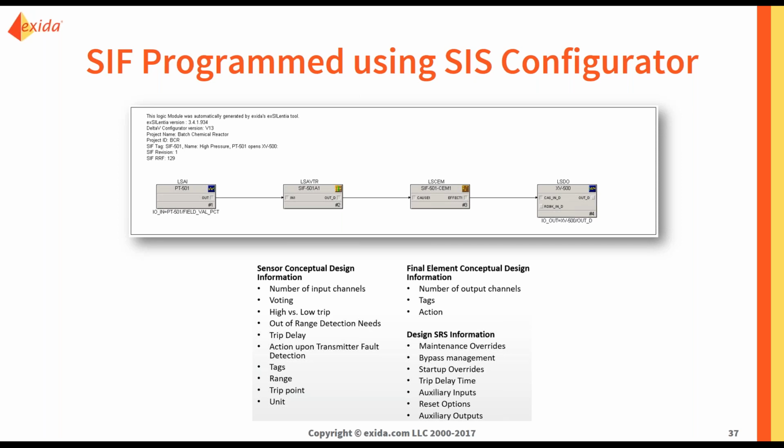For your sensor conceptual design and your final element design, all of the things you need to know, the tags, the action, the set points, etc. are in the tool. And so this is something you can simply import from your Lifecycle tool to your safety PLC. This is a task that usually takes months to do.